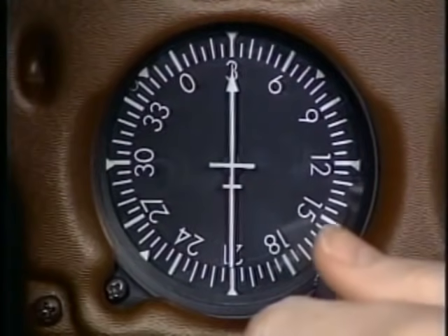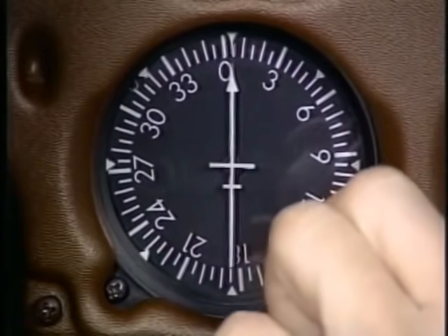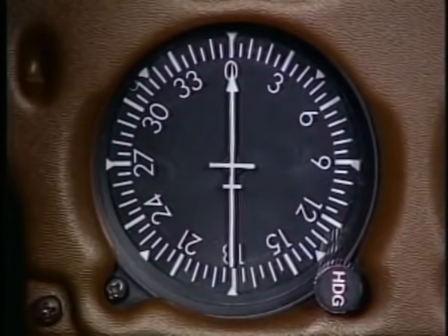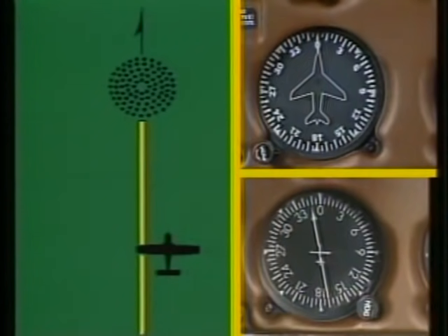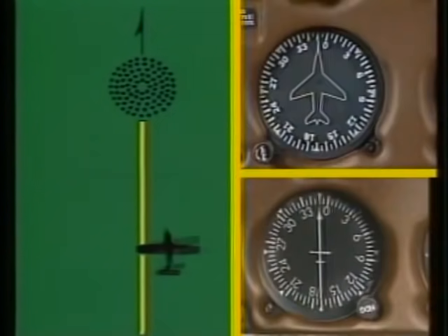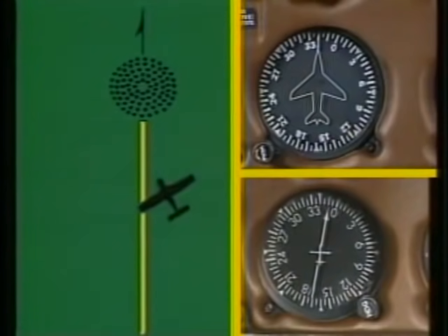Since the ADF does not automatically provide a wind correction angle as a VOR does, let's review the bracketing procedures. In this example, you've drifted right of the 360-degree bearing to the station. The ADF is sensing a crosswind by pointing to 350. To regain the course, you apply a 10-degree correction into the wind and reset the ADF to match your heading. If your heading and relative bearing remain constant, you've corrected for the drift, but you will not intercept the 360-degree bearing. So, an additional correction is needed.